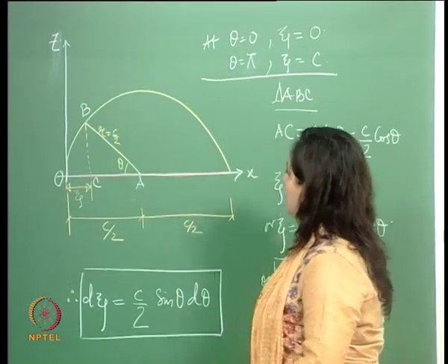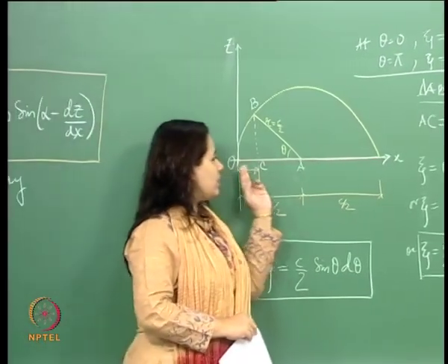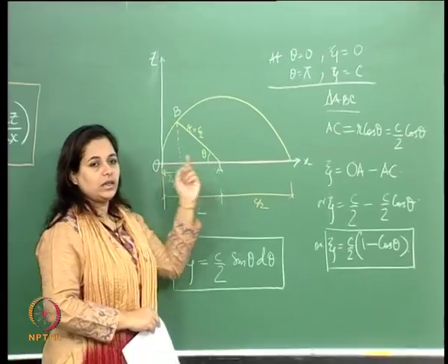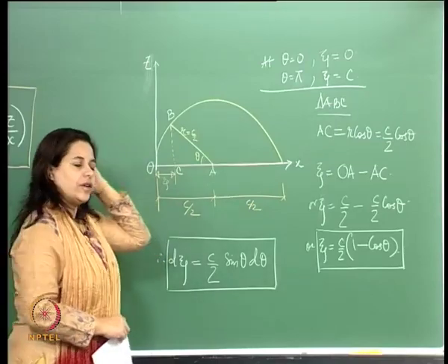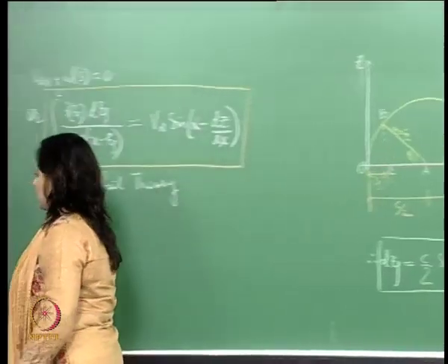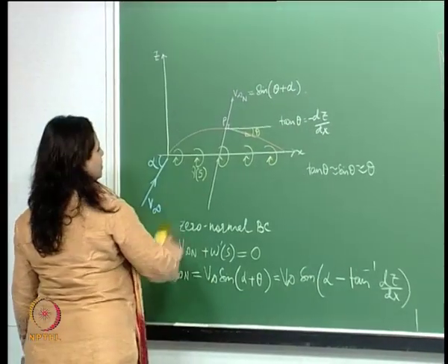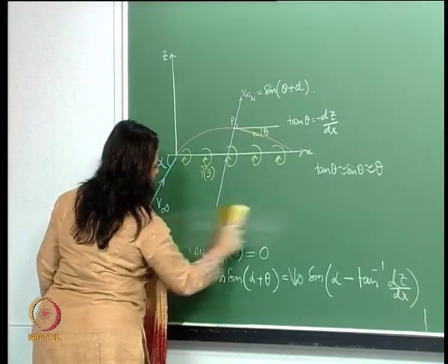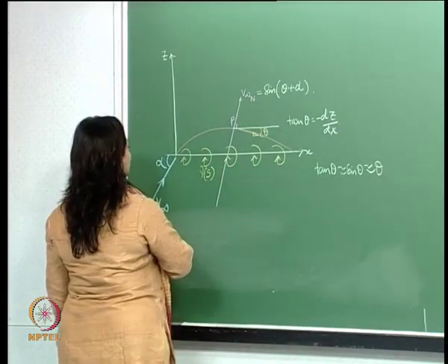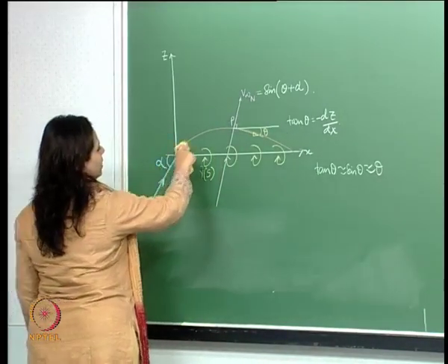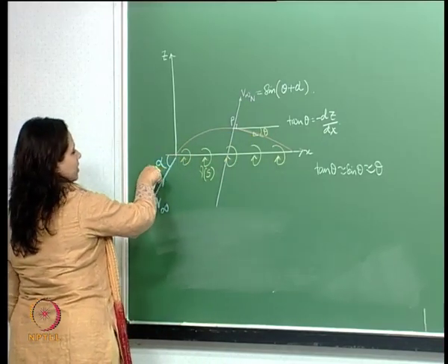Okay. Now, in this particular case, what we have is a flat plate. So, the camber line out here is a straight line which is having an angle of attack of alpha, which would mean what? Okay. So, let us sort of draw this picture out here. What we have is a camber line like this, which is at an angle of attack alpha here.